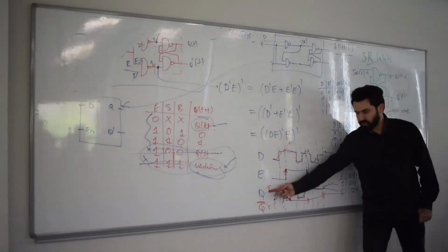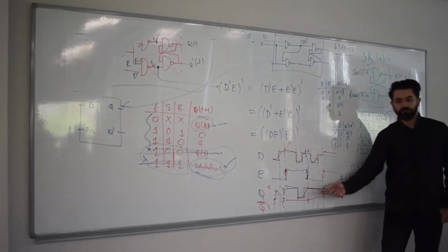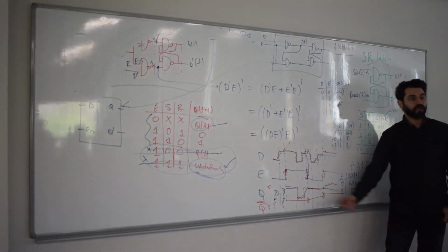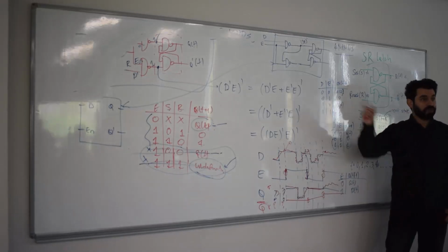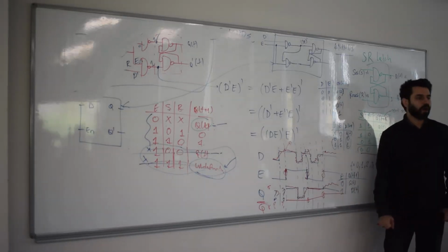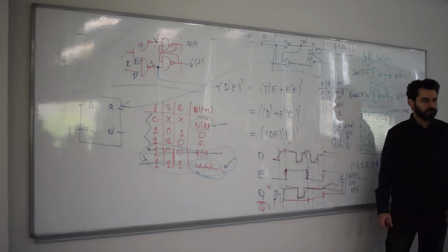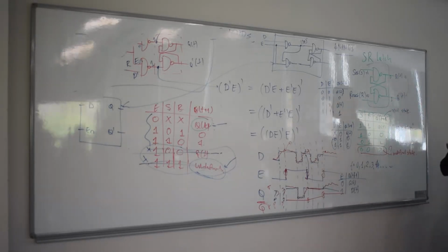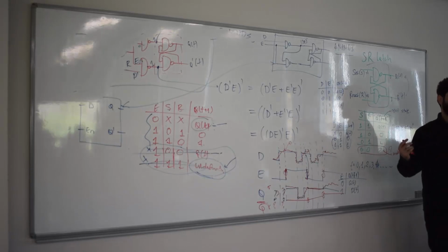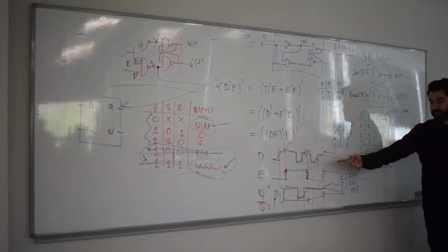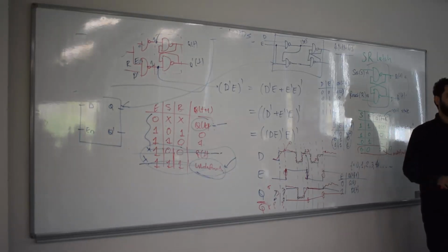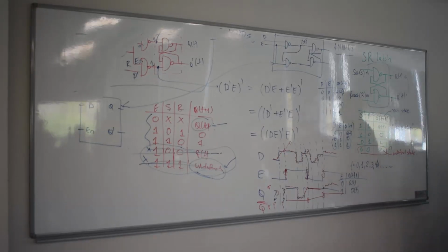That's why latch can work in asynchronous environments, but flip-flops don't work in asynchronous environments. They have got something called a clock, which I'll introduce now. And based on that clock, they make decisions. All synchronous digital circuits use flip-flops instead of latches because of that noise characteristic. Can latches be used in synchronous circuits? Yes, they can. But again, their noise problem is still there. So we don't want to bother ourselves with the noise. That's why we use flip-flops.